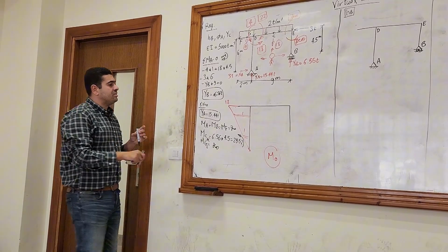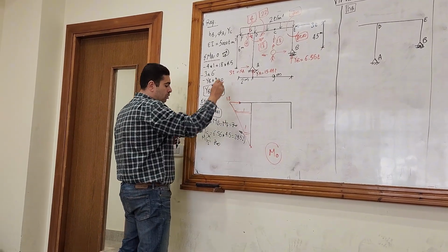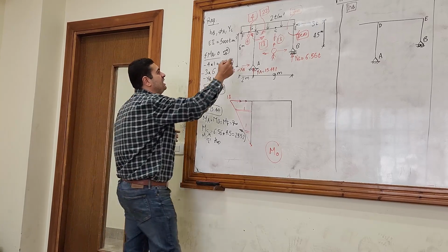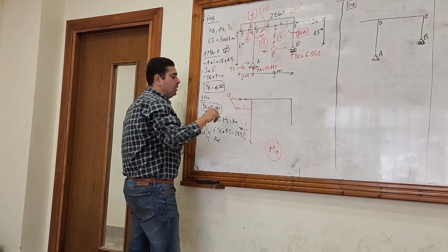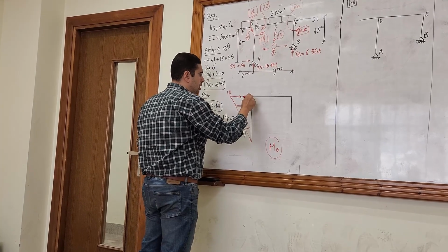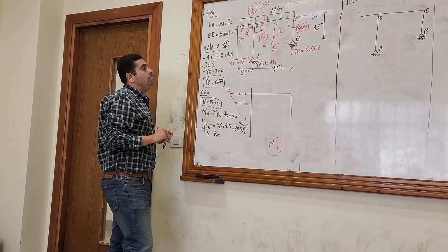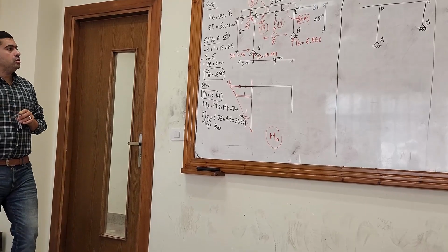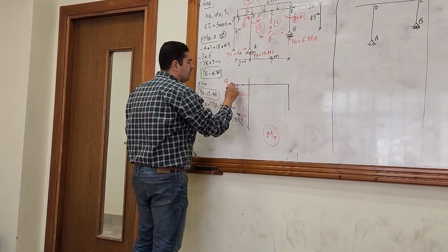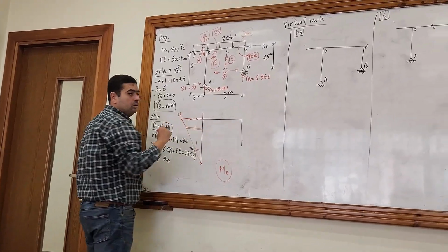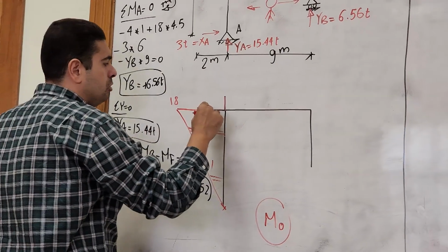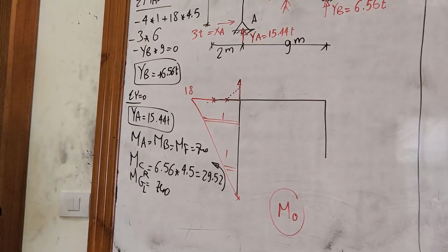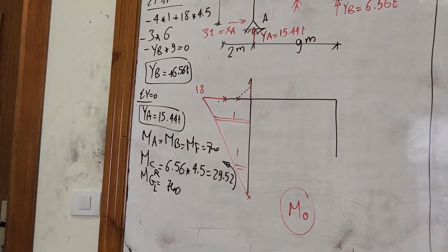The moment at F is 0. The moment at G is 0. The moment at D is 4 and the tail is up, so 4 up like this. But here the member has a uniform distributed load. So let's join 0 with 0 dotted and 0 with the 4 dotted. And here the correction will be a second degree parabola.